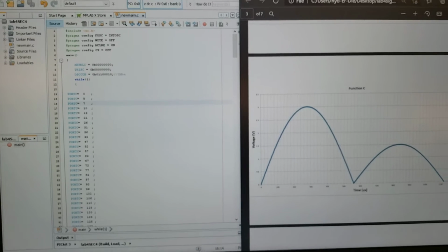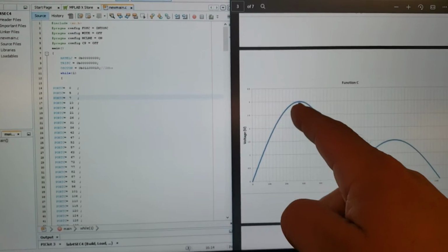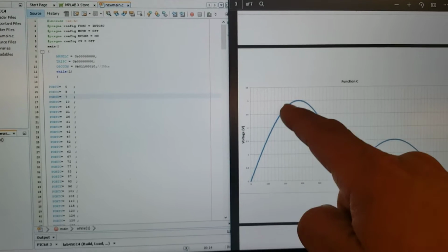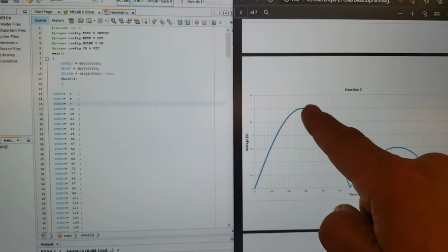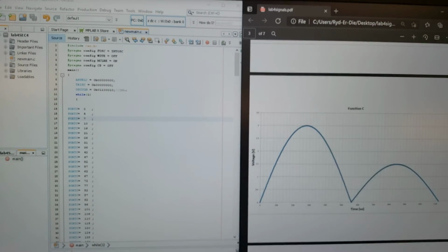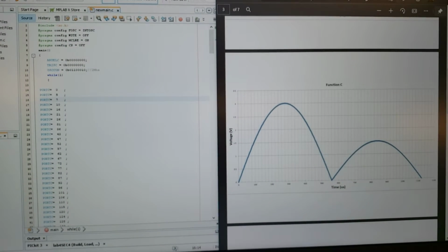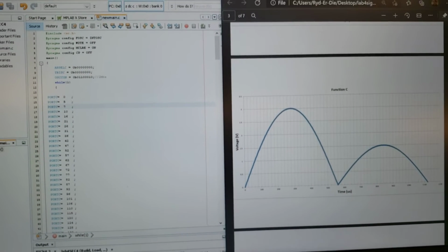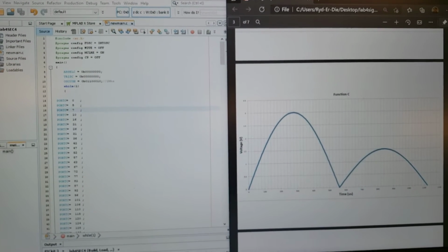We divided that by 2 to give us our 90 degrees to take advantage of the fact that sine waves are mirror images of each other. So we can take the first 90 degrees and then just mirror those values to give us our 90 to 180 degree to reduce the number of points we actually need to plot.